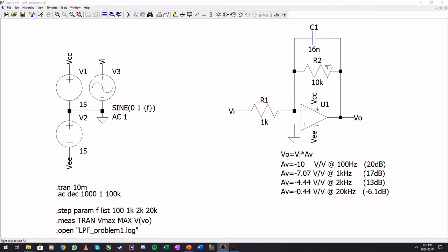So I went ahead and set up our filter, and I already did some measurements in the Bode plot. We will get to that in a moment. So first off, I set up our signal here for AC 1. So that means that we don't have to deal with any strange dB conversions in our Bode plot. So always put this on AC 1.